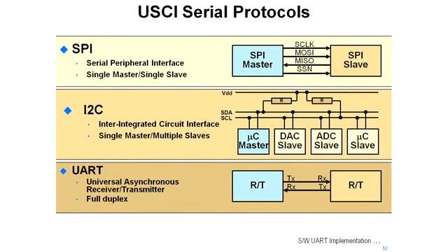The protocols offered on the USCI are SPI, I2C, and UART. SPI is the serial peripheral interface. The intent with this is to offer you a simple way of connecting up a SPI master to a SPI slave. Now, the master doesn't have to be the microcontroller. It can be an ADC, and often you might have it be the ADC or a timer where you want that to be able to wake up the processor. There's only 4 connections in that, the S clock and the rest of the signals that you see there.